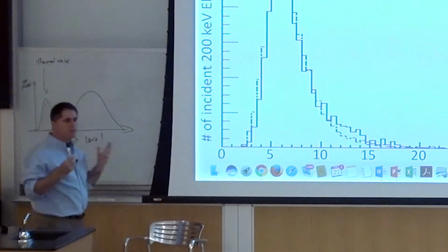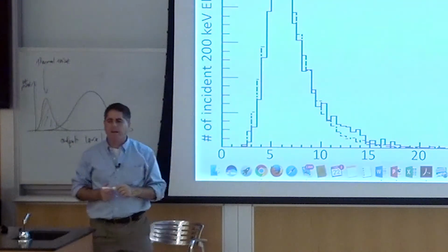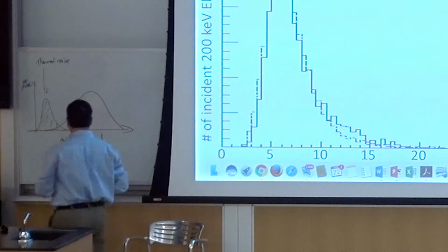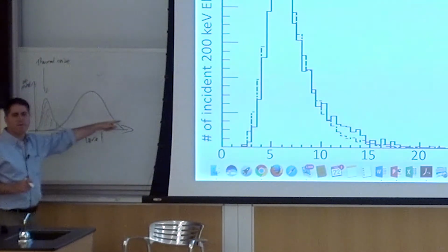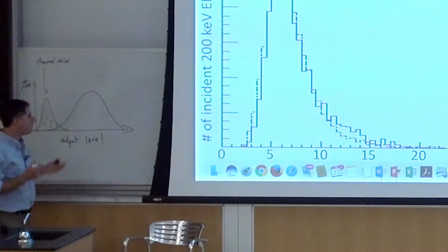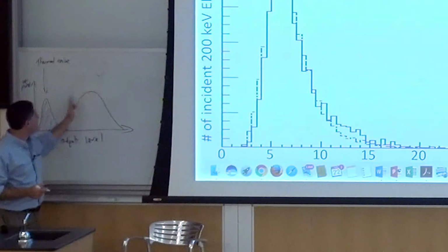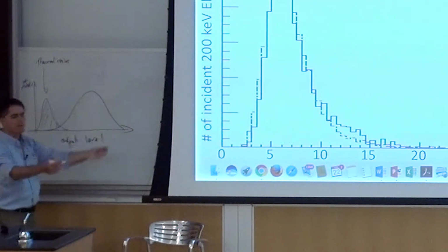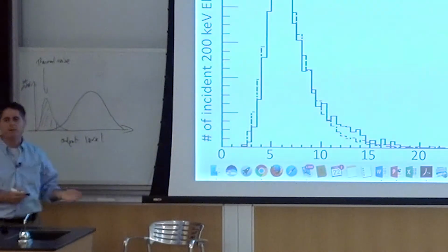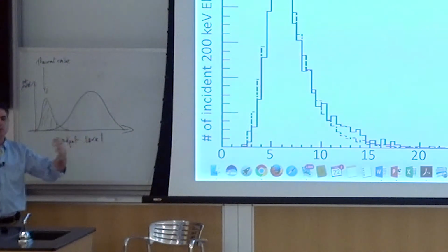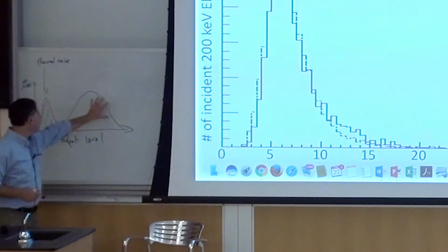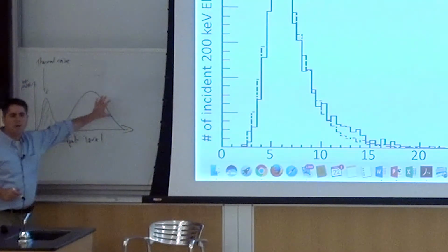Now, what pulse counting does is I know that each electron produces a pulse that will be somewhere in this envelope over here. A particular electron might have this shape. One electron will hit my piece of silicon and generate 20,000 electron-hole pairs. There'll be an energy distribution to it, and it'll fall somewhere in this range over here. They don't all have the same energy.